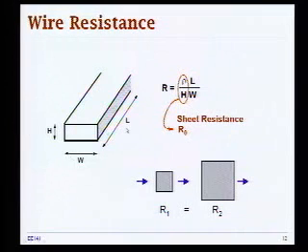And then we also derived this simple model assuming a wire that is H tall, W wide, and L long. We have this equivalent resistance of a wire that is given by rho over H, that is sheet resistance, multiplied by L over W. Now, the reason why we wanted to actually keep the height of a wire the same is not because of capacitance, but because of resistance.